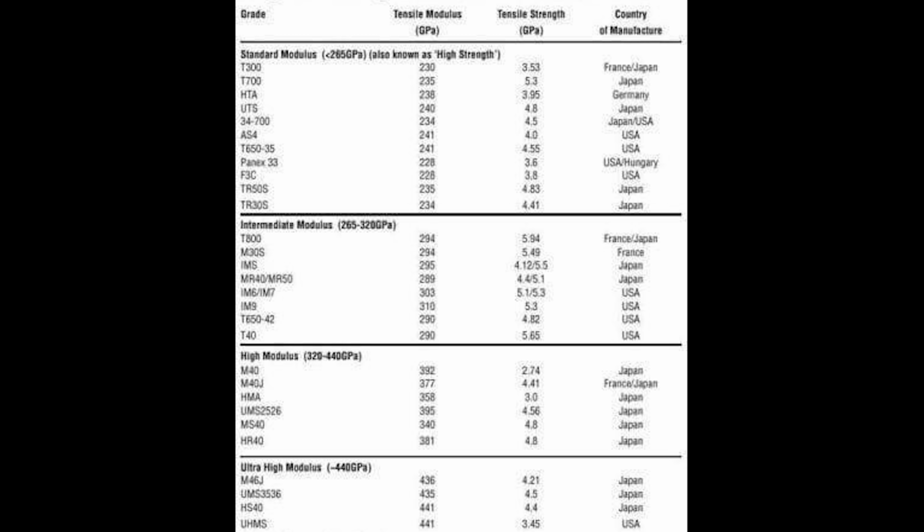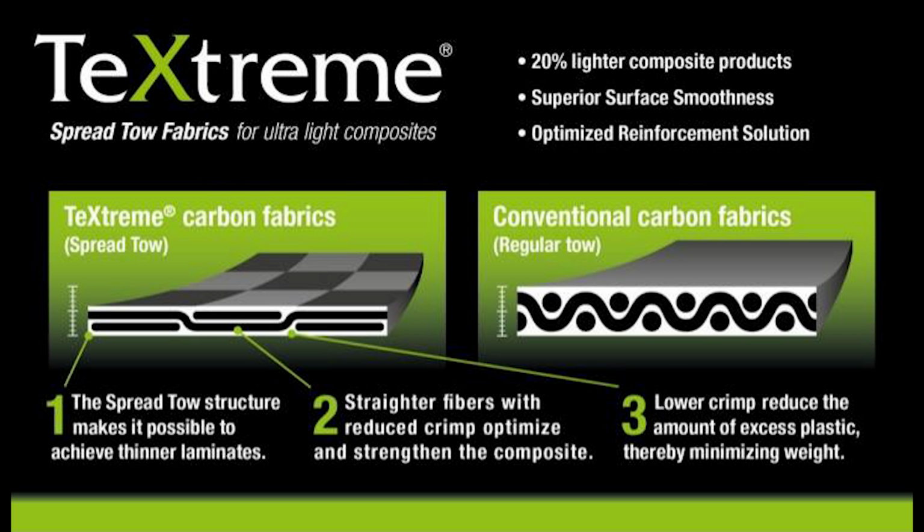One of the biggest purposes of having a weave on the outside is impact protection for the layers underneath, especially in a 3K fabric, because the UD is very sensitive to impact. So you want to protect it, and the weave is very good for that. Your product is a woven sheet, but it's very thin, so the fibers aren't deflecting much as they weave up and down.